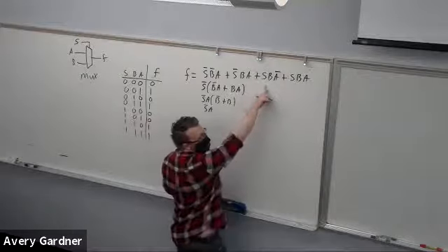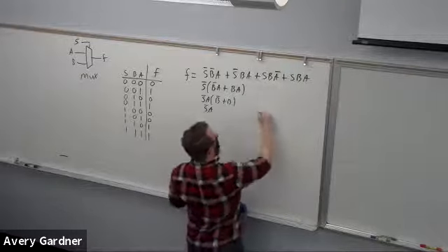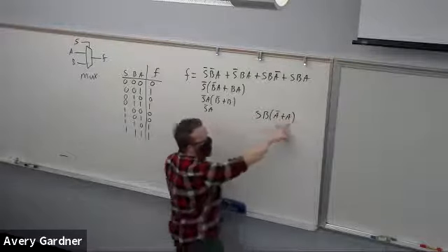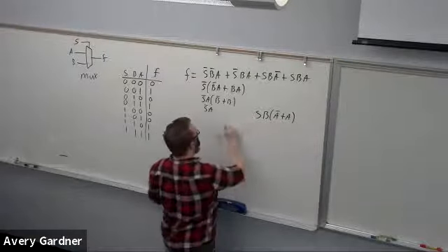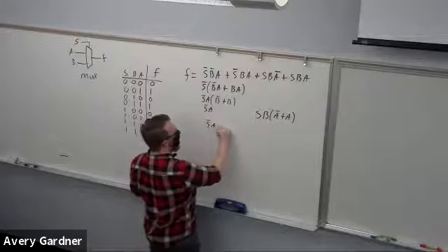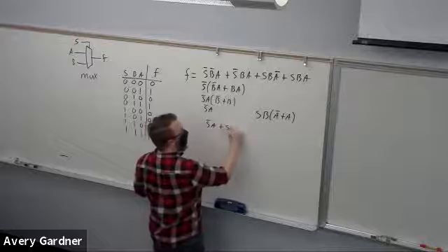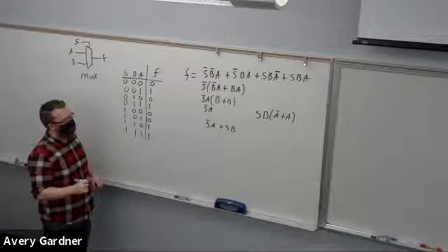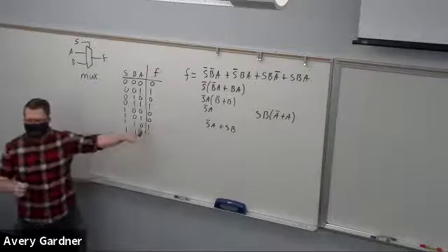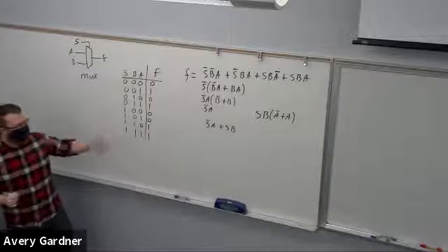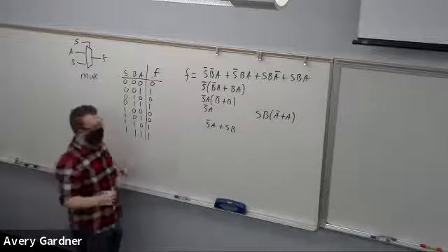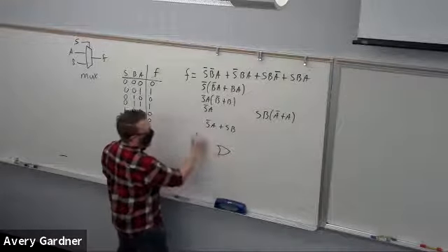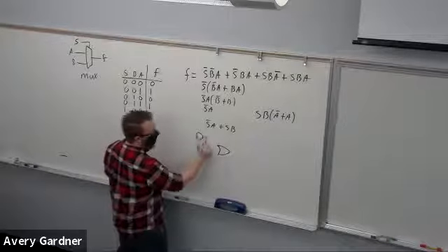Here, same, yes, excellent. So I'll just drop this all the way down here. S B times A bar or A goes away. We end up with S bar A or S B. Well, that's a pretty nice, easy circuit. I could actually do something probably if I was using XOR gates, but let's just leave it at ANDs and ORs for now. Now I have an output OR gate. I have two input AND gates.